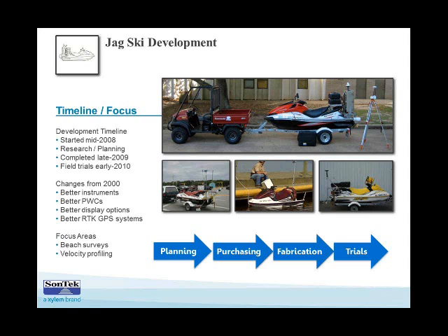So this is just ASCII exported data from the data collection sessions in River Surveyor Live, and then exported to a second software package for viewing and plotting. So if we zoom in, say on the channel survey, you can see my vessel tracks and the soundings there, just from the single beam unit, so looking at just the vertical beam transducer measurements there. And this was all very capable and doable. It required a little bit of work on the backside to make sure that your data were very clean and you were getting reliable data.